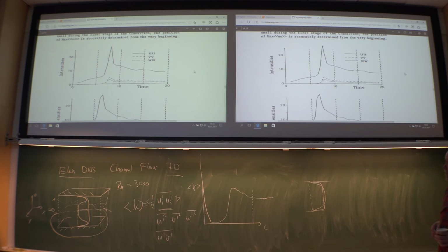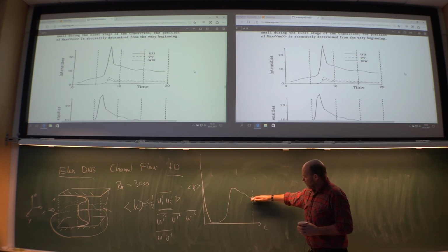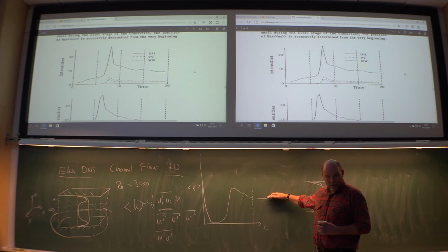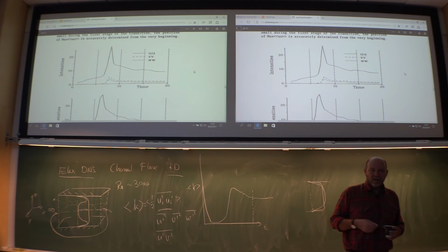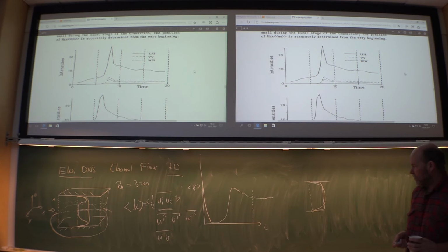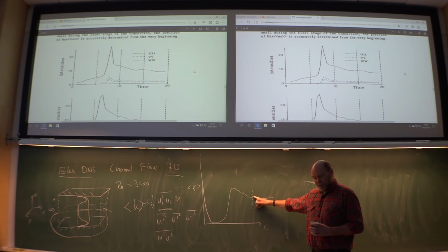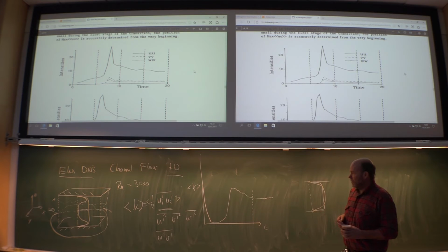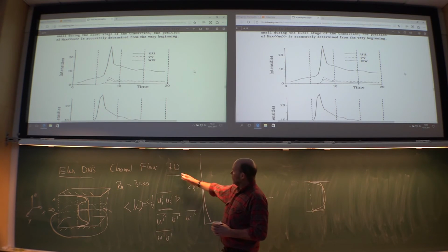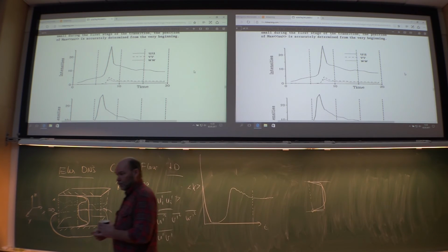So it was expensive to build up a correct steady state level here and finally say that yes, now I have a fully developed turbulent flow. So it's expensive actually to just get things started. And from here on I could now start achieving statistical results to getting an answer to my problem. But it was not just switching on the on button here. That I can show you.